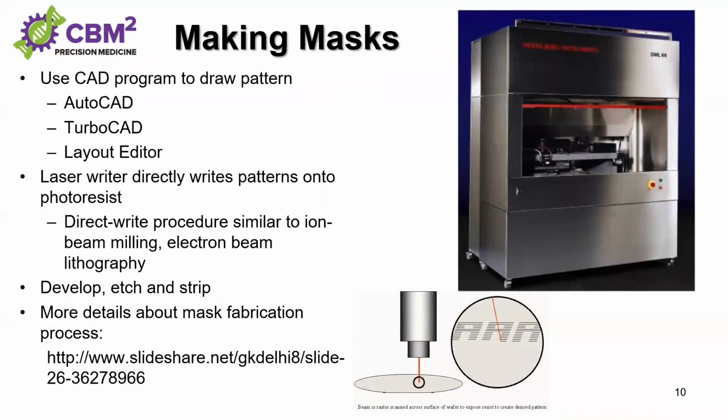So basically you also use optical light to draw the patterns that you want to have. It's also another photolithography step, but in this case we use not a parallel process but a serial process to custom write the structure you want to have. And then you do the same procedure, developing, etching, and strip, so that you partially remove some of the chrome layer on your mask substrate.